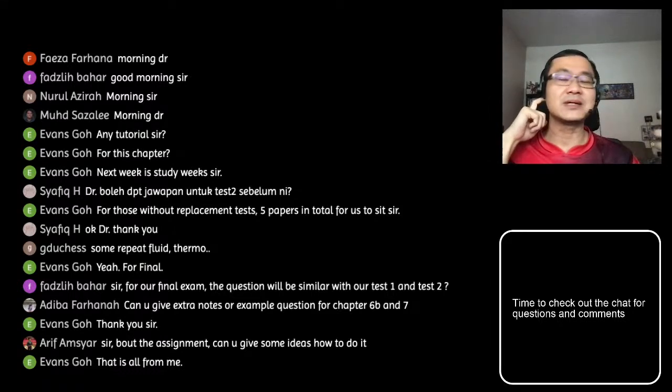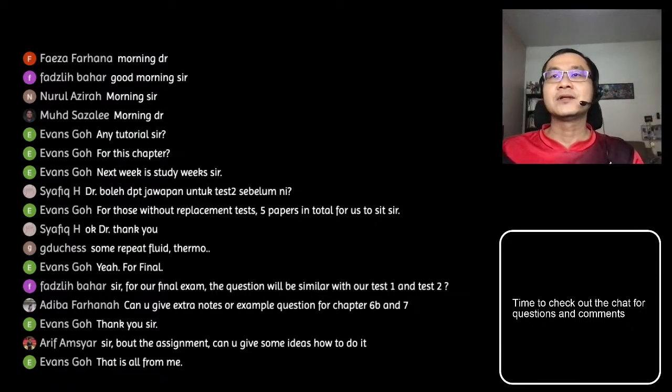Eventually you will still get a PID transfer function which has two parts. And I don't limit you to the pure or ideal PID. You can use the lag-lead compensator to act as a PID control. So it's up to your creativity.